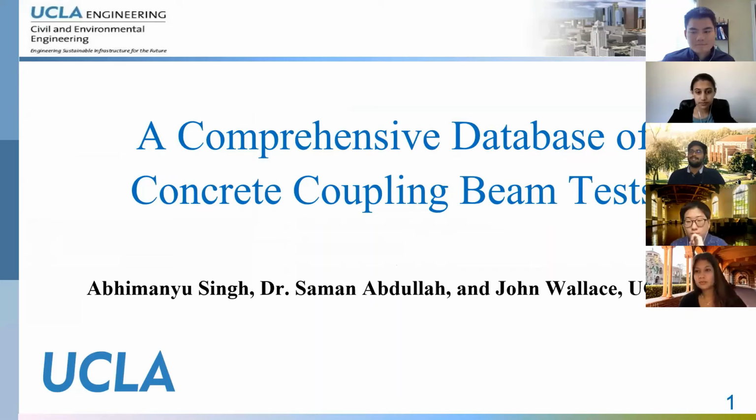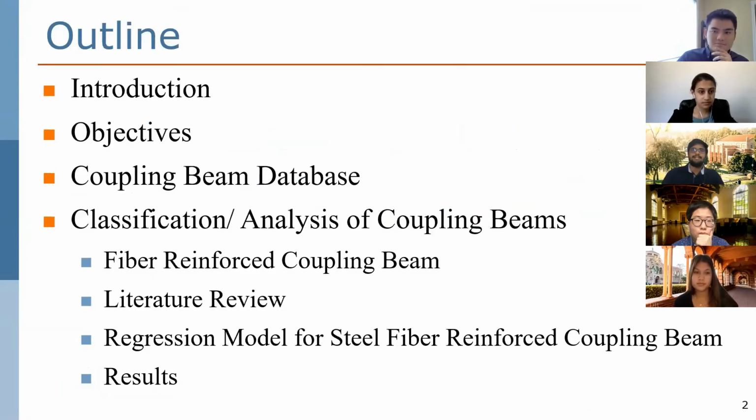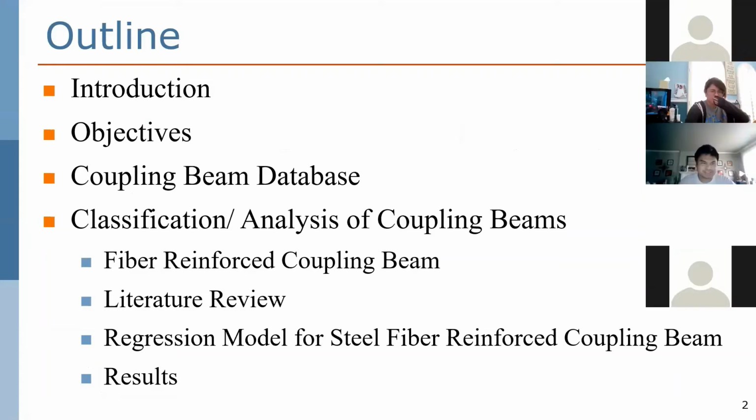In today's presentation, I'll be going over a brief summary of the database and the analysis of fiber reinforced concrete coupling beams and its shear strength equation. So just an outline of the presentation, I'll be going over the introduction of coupling beams and my objectives, then a summary of the coupling beam database, and then moving on to classification, analysis of coupling beams, and narrowing it to the regression model for steel fiber reinforced coupling beam.